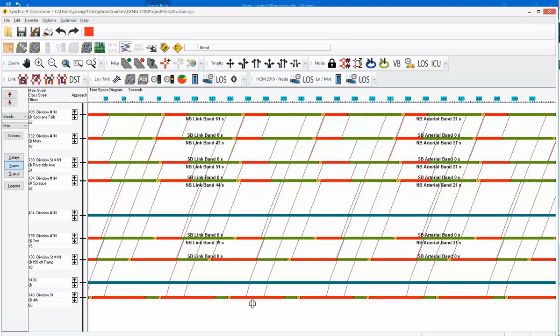And so this is a way of analyzing this. At this point, you see that 4th Street intersection, which is on the south side of the freeway, is not really linked to what's happening on the north side of the freeway, which makes sense. But we start to see some fairly decent progression, right? There's a certain amount of vehicles that can make it all the way through these green ones. And the distance between one intersection and the other, where the beginning of that green starts, that's what's called the offset. So that's one way of visualizing that.